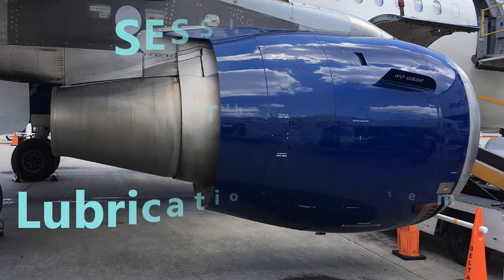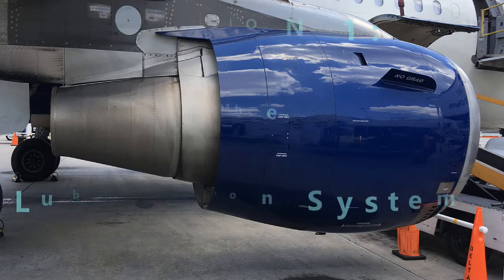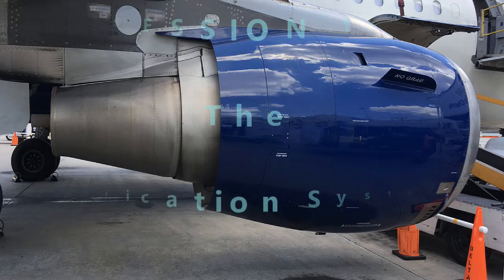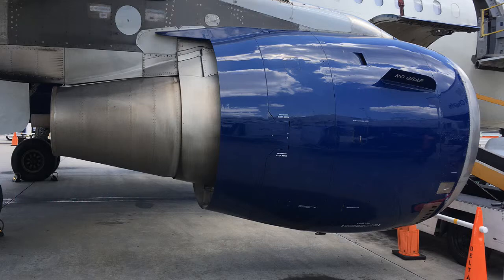There's a range there, but don't get hung up on numbers. The main thing is looking at your indications and where those indicators should be on the ECAM. But it really is somewhere around 35 psi. The oil pressure transmitter enables that oil pressure within the system to be monitored, obviously, so that it can be showing up on that ECAM.